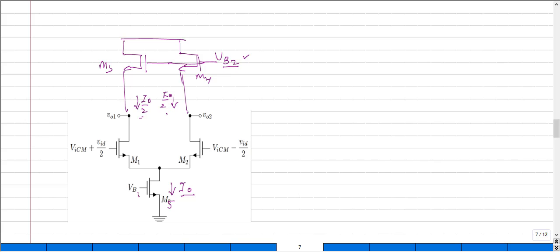And we want this feedback, the common mode feedback circuit, to adjust this VB2 so that it always maintains this relation. Now let me go for a simple case by shorting this node and then putting a kind of feedback, something like this. Now can this feedback mechanism establish the common mode feedback, or can this kind of feedback that I've drawn work as a common mode feedback circuit? So what would be the answer? The obvious answer would be yes. You might not get surprised. It's yes. Then I need to know what is the output common mode voltage for this, right?